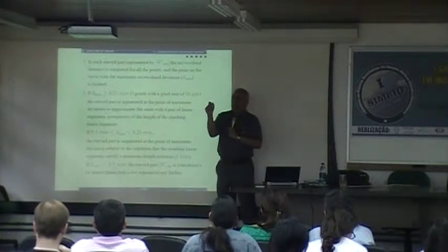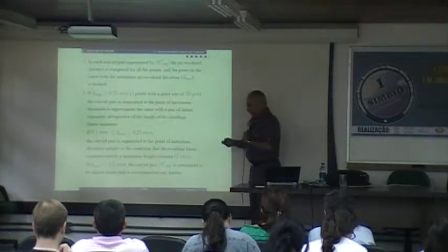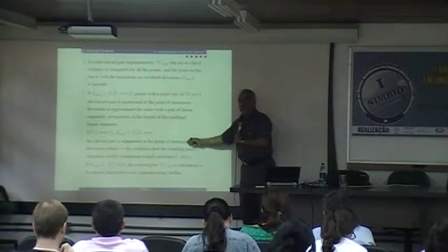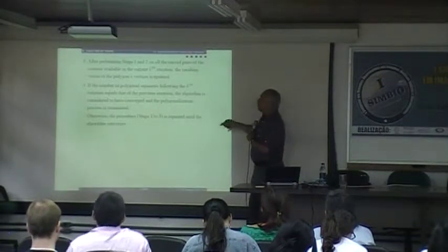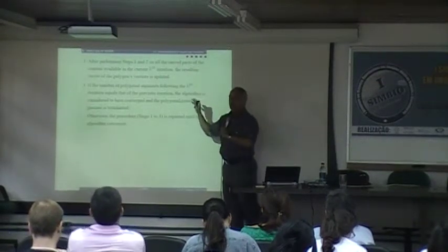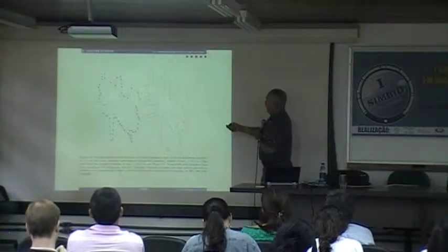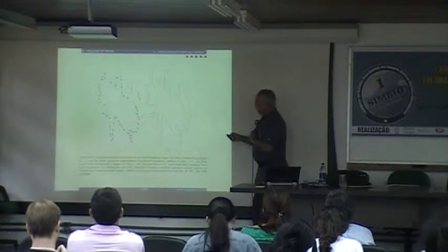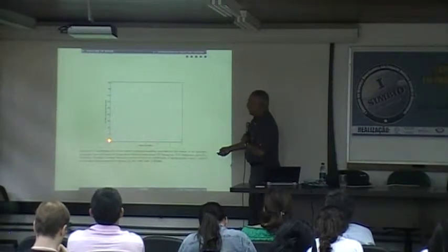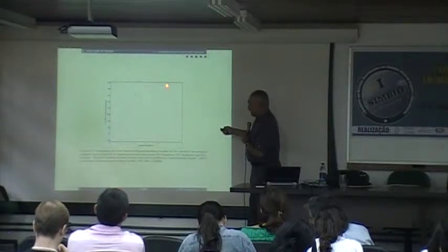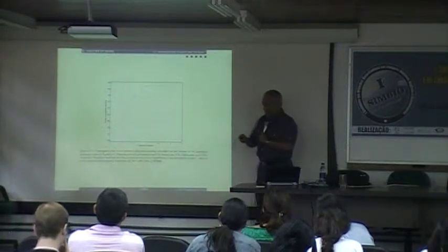You don't want sides of the polygon being very small, 1 pixel. You say minimum 1 millimeter, and so on. These are particular to the application, so you don't have to be concerned much about that, and iterate. Iterate this until there are no more new vertices added to the polygon. And the result is this. So in the case of here, the iterative procedure starts with 58 points and saturated or converged at 146 in 5 iterations. So it is fast.